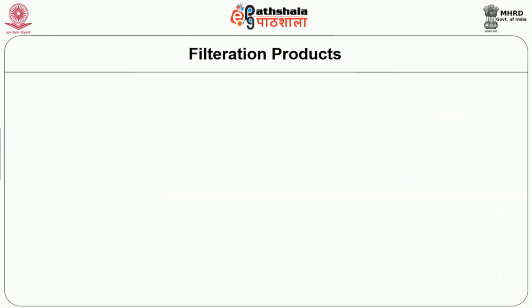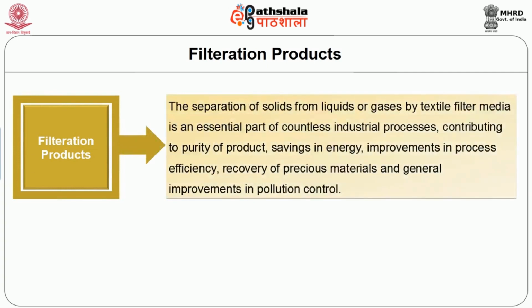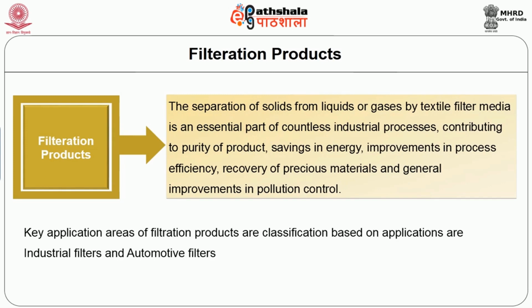The next concept which we will be seeing is filtration products. The separation of solid from liquid or gas by textile filter media is an essential part of countless industry processes, contributing to purity of product, saving in energy, improvement in process efficiency, recovery of precious material and general improvement in pollution control. Key application areas of filtration products are classified based upon application as industrial filters and automobile filters.